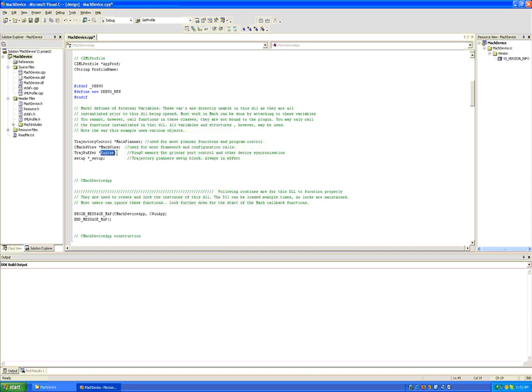Changing variables in Engine can trigger movement, can get direct access to the ring 0 ports and pins and various things inside your kernel. And then there is setup, _setup, which is a pointer to the trajectory planner, RS-274 information, and various configuration data of your trajectory planner.